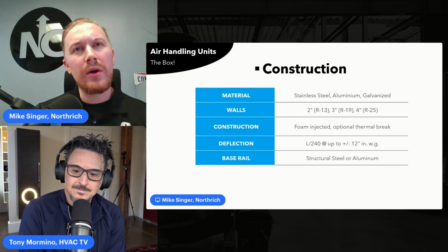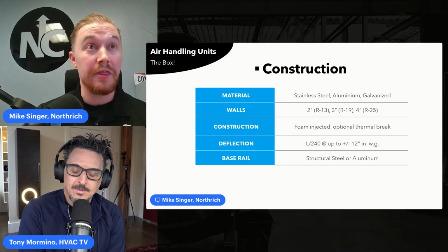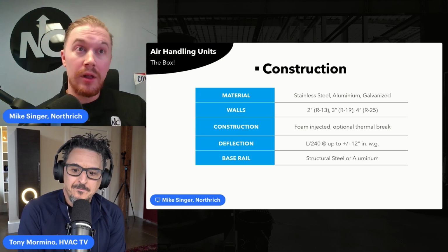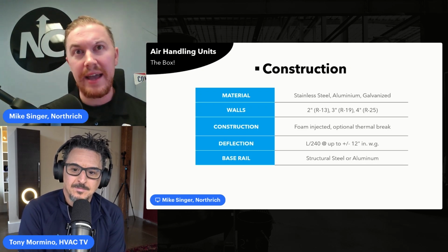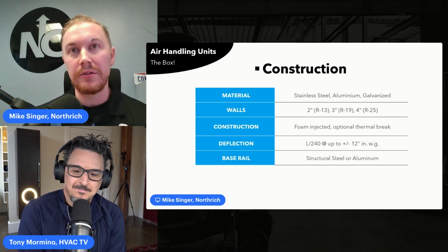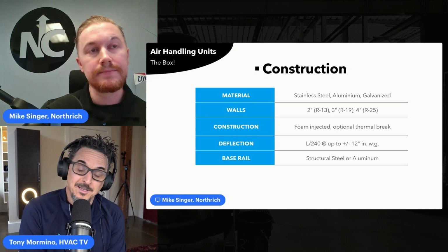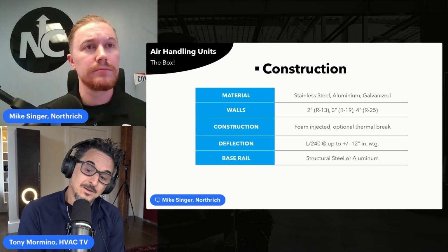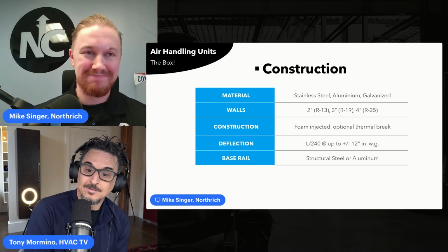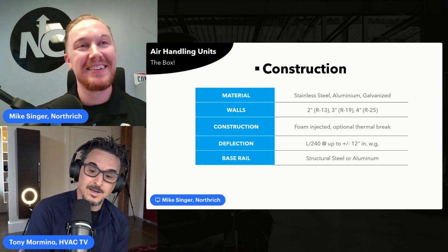Yeah, you wind up having to increase the wall thicknesses, the actual metal, because you lose the structural integrity that the injected foam provides for the unit when you go to the fiber fill. So it could be a more expensive unit when you go to fiber fill. It's funny. I was thinking when I started, single wall was the standard, foil faced fiberglass. Wow. And double wall was an upgrade.